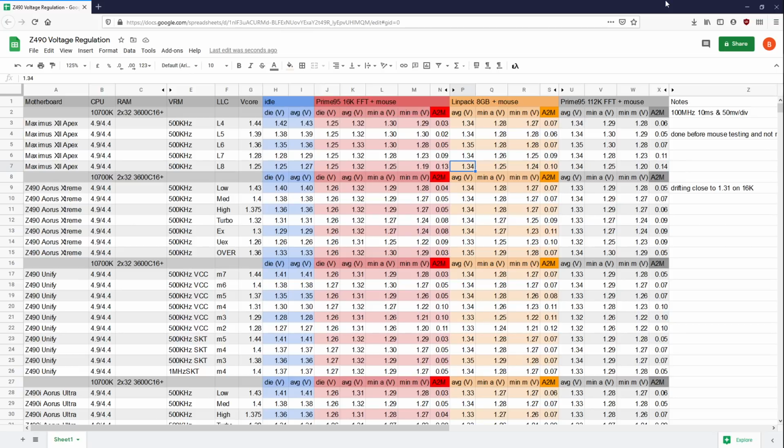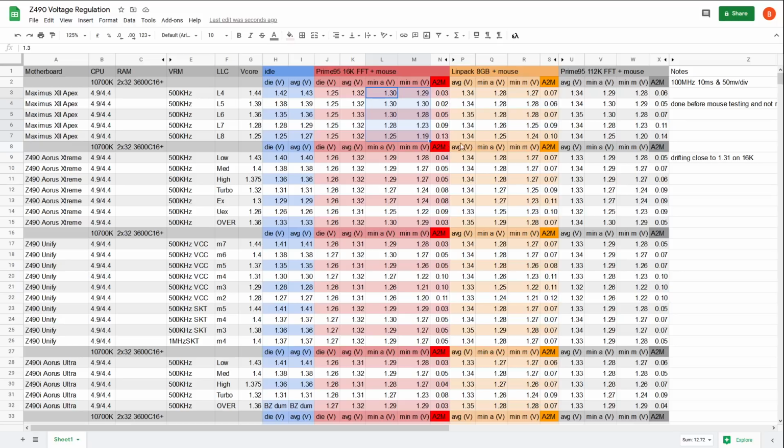So we don't have to worry about overshoot. We have undershoot measurements, so I don't care about the overshoot measurement, right? From a regulation perspective, it's just kind of a health perspective for the CPU, and it's fine. None of these boards was anywhere near concerning levels of overshoot. Even if we scaled up the voltage, it still wouldn't be concerning.